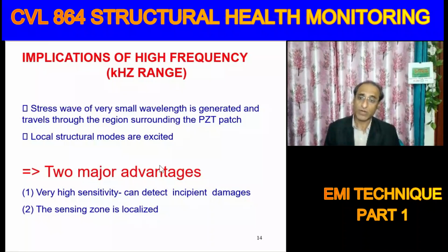So this has advantages. Number one, it has very high sensitivity, so that we can detect incipient damage, and the other point is that the sensing zone is localized. Why localized? Because as we increase the frequency, the energy tends to get limited to the area surrounding the piezo patch only.